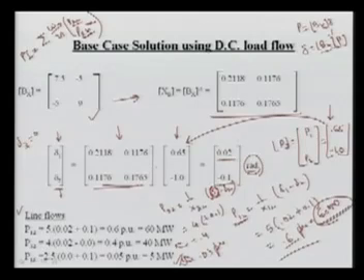So you can see how fast it is, and it is called DC because we have ignored the voltage. We are only taking these deltas, and these deltas give power flow directly. Although these power flows are not so accurate because we have ignored the losses and the voltage, for rough ranking it still gives very good results for real power flow security.